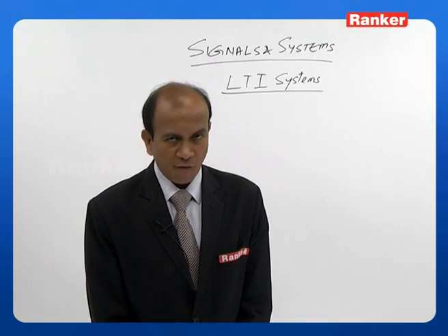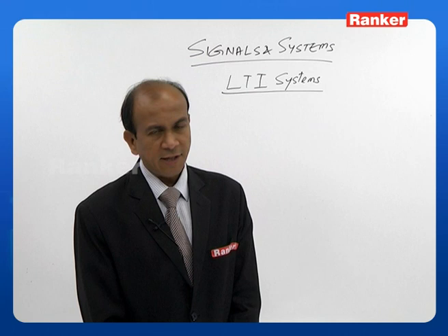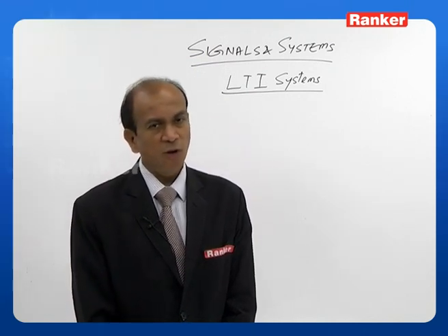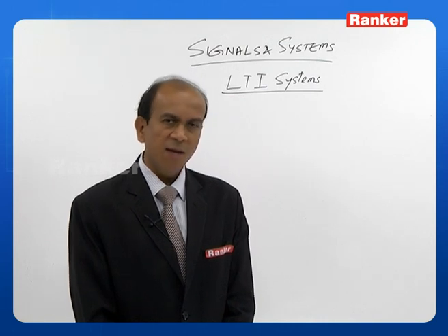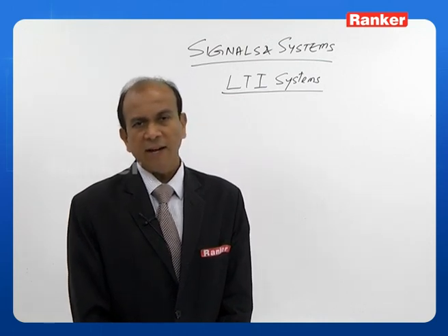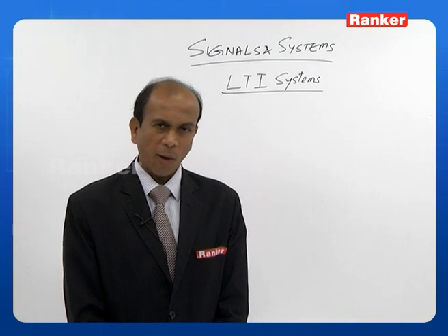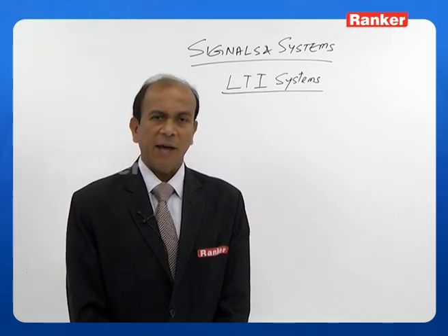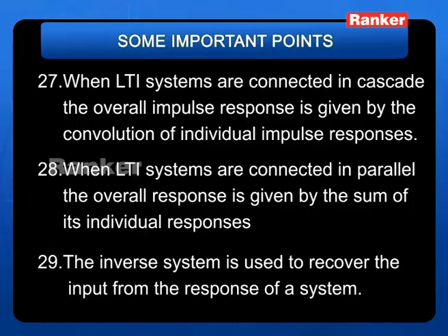That means, if you connect two LTI systems in cascade, the overall response will be the convolution of the individual responses. Whereas, if I connect LTI systems in parallel, the overall response will be the sum of the individual responses. 29th point. The inverse system is used to recover the input from the response of a system.